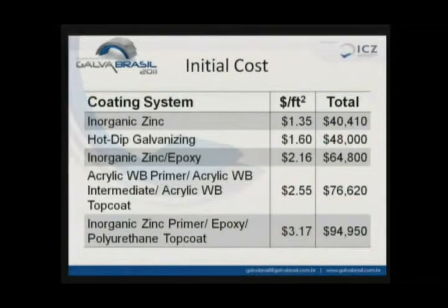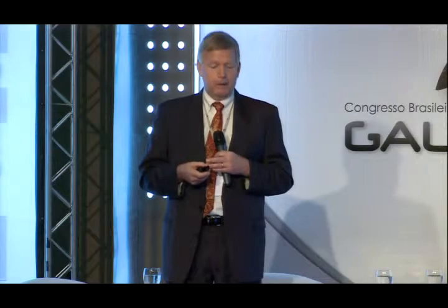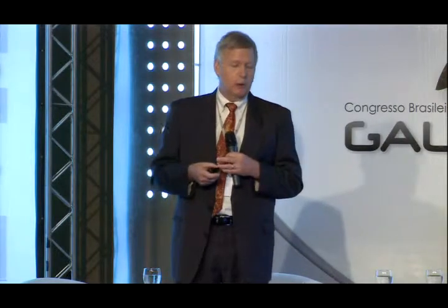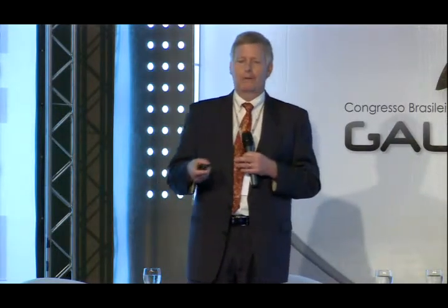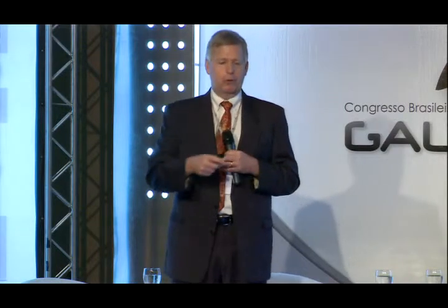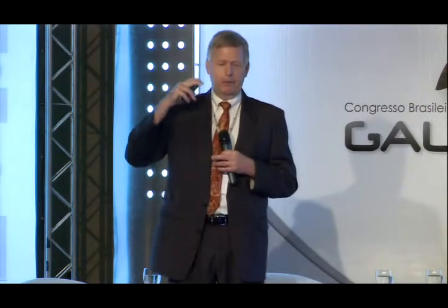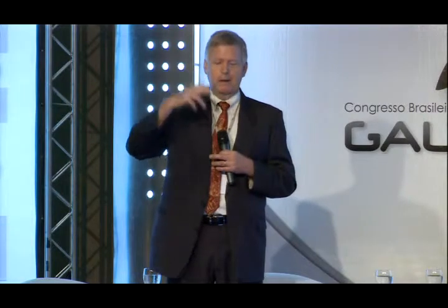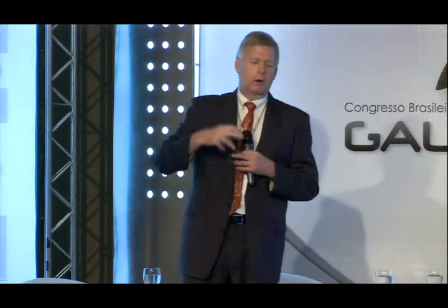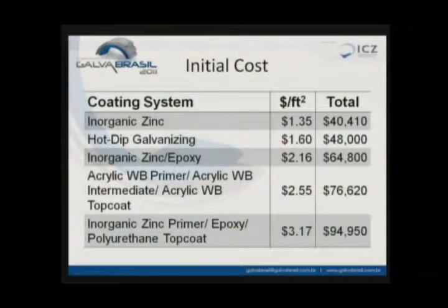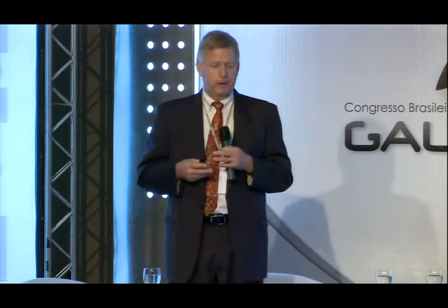So the results are a little surprising. They show that hot dip galvanizing, which after all has a life of many years, 50 years is not unusual, and this, I'm sorry, is dollars per square foot. But even if we go to reals per square meter, the ranking is the same. If you are making your conversions, there's no change in the order of the numbers, but we just use dollars per square foot here. Inorganic zinc is cheaper. Then you have hot dip galvanizing, and then inorganic zinc epoxy. These are all very near together.